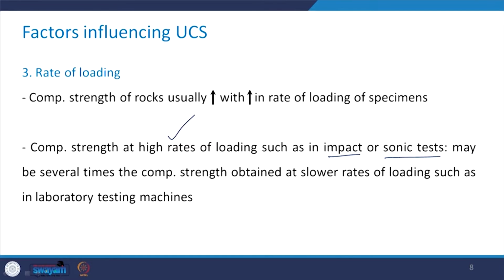When you conduct the test at such high rates of loading, the strength characteristic can be several times higher than the compressive strength test which you conduct at a slower rate of loading in the laboratory testing machines. So one needs to be careful about deciding the rate of the loading.